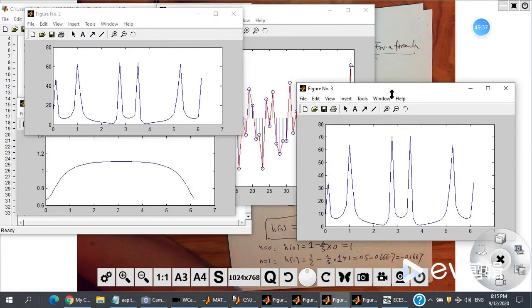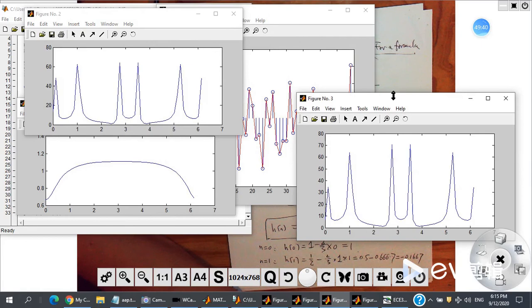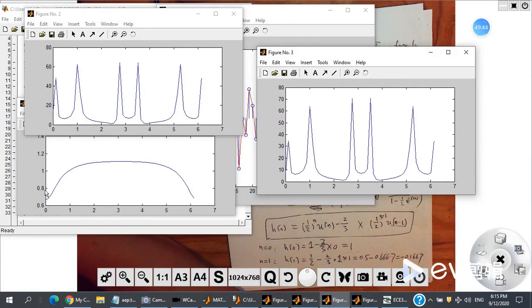and this is the output. So we know the input in the frequency domain times the frequency response gives you the output, right? This is the frequency response. You see, for the frequency in the middle, around pi, that is high frequency. For the high frequency part, the system magnitude is close to 1. So for the output side, for this high frequency part, the change is just a little bit. You see these 4 peaks actually correspond to 2 frequencies. The change is just a little bit,